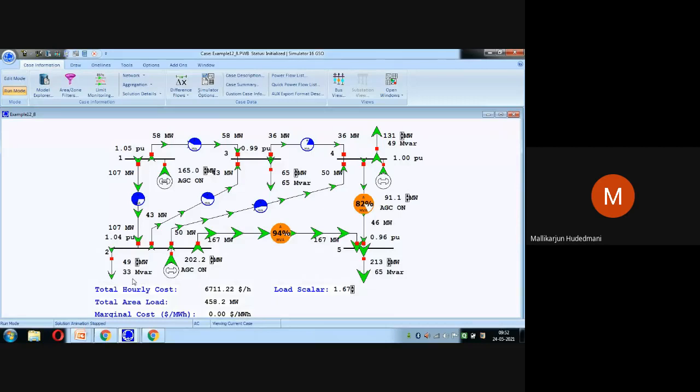They are called loads. So my interest to show you here is AGC, automatic generation controller, on. AGC on here. So what is my interest over here? When automatic generation control of this connected power system is working, interconnected by themselves, when the load change occurs, how is that automatic to the change in load, these generators start accelerating their generation, increasing their generation to make the P balance. I wanted to project that to you.